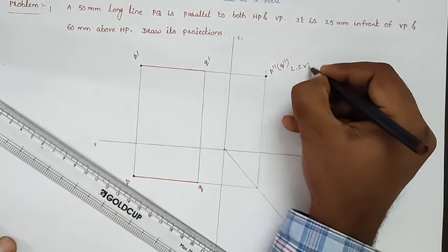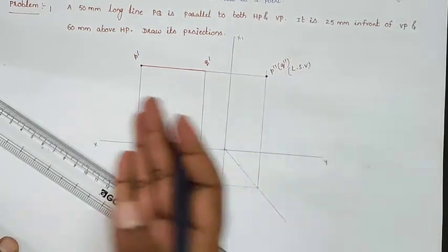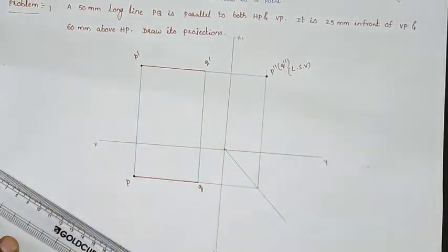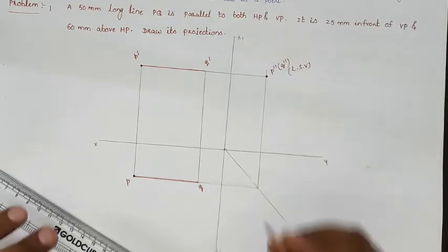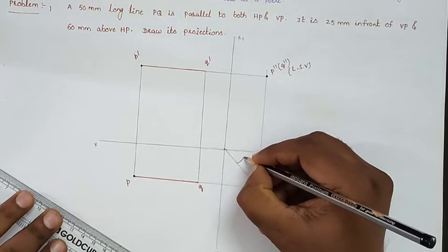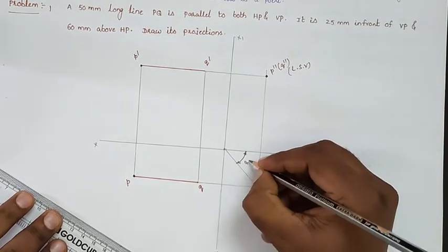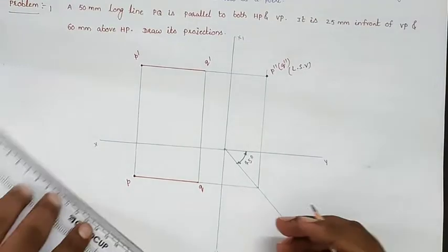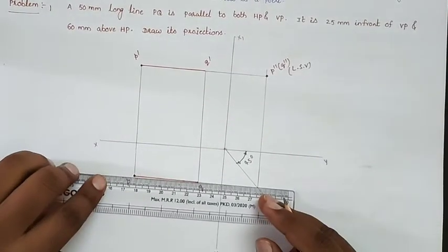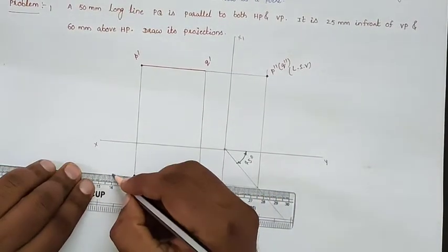We will draw the right side view also. For drawing the right side view, we will draw another reference line at the left side of the front view and we will construct the right side view. I am representing only the left side view here. After drawing the side view, we will draw the dimensions which are given in our problem. So this is our problem solution.